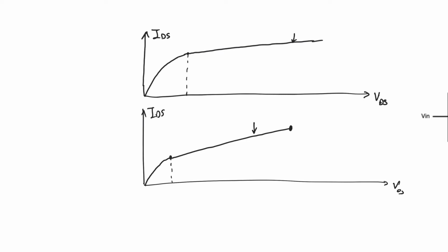Also, at relatively early voltages, we find that the current of the transistor starts to increase very rapidly. What's happening here is basically punch through. When punch through occurs, which happens at V punch through, the transistor becomes almost a short circuit, because we have a region of very low resistivity between the drain and the source. We already discussed how punch through is actually a failure mechanism for the transistor.